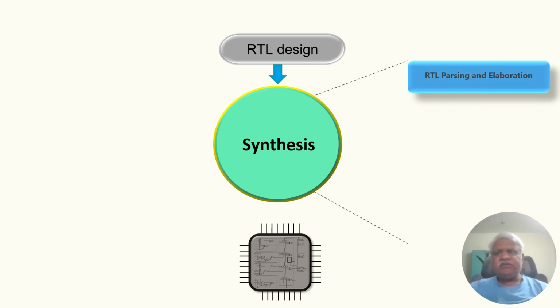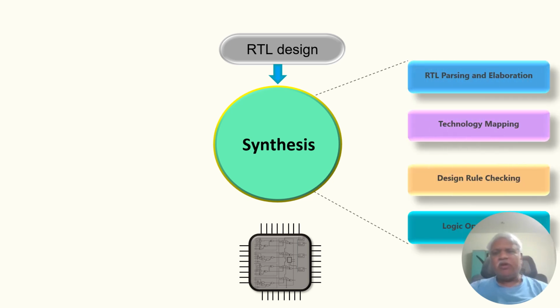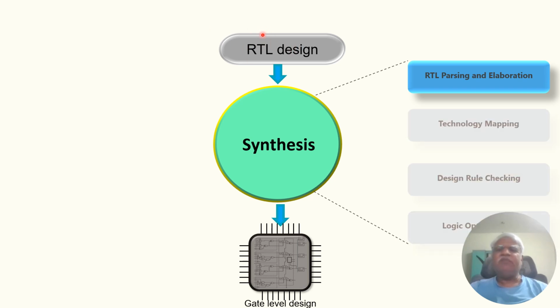During this synthesis part, especially the RTL compilation and elaboration step, during the compilation step, it basically parses the HDL code and ensures that it is syntax-wise correct, the ports are properly specified, and the connections are properly hooked. So all these checks will be ensured, and it will ensure that the compiled code is ready for elaboration.